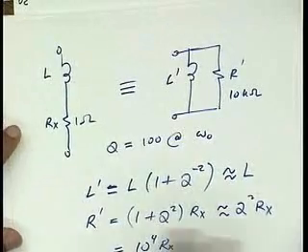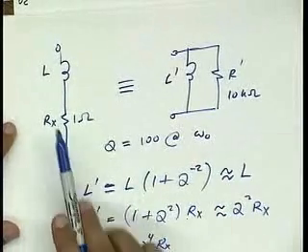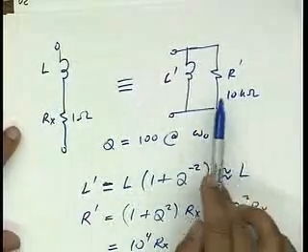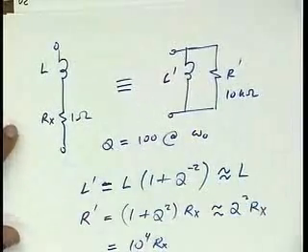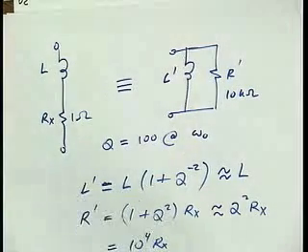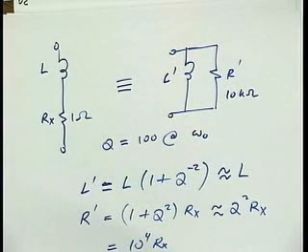Okay, so this is very simple. All I'm doing is transforming a series XR circuit to a parallel XR circuit. Okay, questions or comments? Yes. In the limit case, when the DC where the Q equals 0 for series LC, can you explain why the parallel equals series resistance? Why RP equals RS in that case?